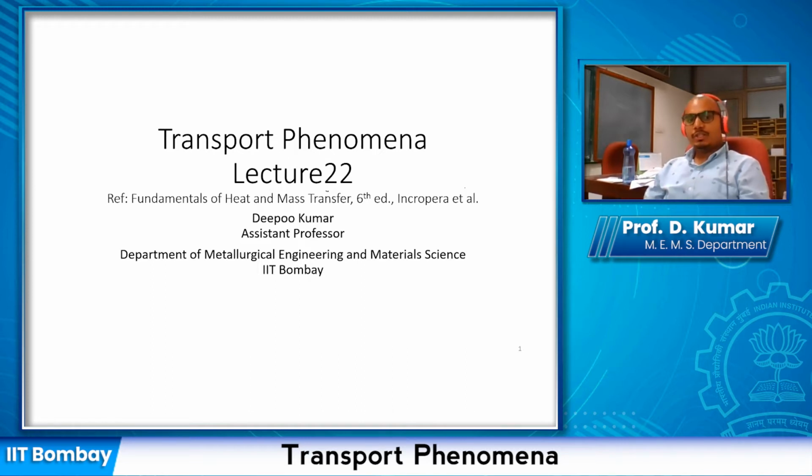As you know, as an engineer we should be aware what correlations are available, and how we can use them under what conditions, because the correlations are developed under certain conditions. As you would have seen in the previous lecture, we talked about some correlations that are developed only for Prandtl number, let's say less than 5 or maybe greater than 5, or for liquid metals where Prandtl number is much smaller. So you can use them only under those circumstances.